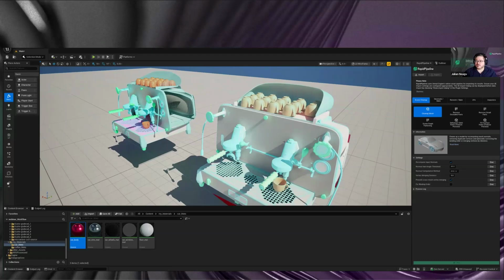So basically, outside of the Unreal plugin, we also have, as I said before, quite detailed settings to fine tune how the winding order flip actually works. There are different options. It could work per triangle. Right now, as a default, it always works per mesh lump, meaning not only per mesh, but any kind of connected pieces of triangles. So the smallest unit of a mesh would be checked against the sky and then flipped as a whole instead of just flipping per triangle.